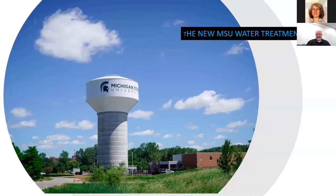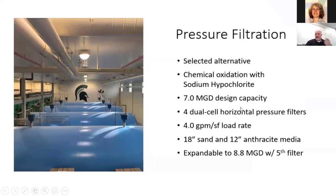Excuse the technical difficulties. Okay, pressure filtration. We have 4 horizontal filters. They're a selectable alternative. Chemical oxidation with sodium hypochlorite. Design capacity for the plant as it's presently configured is 7 million gallons per day.